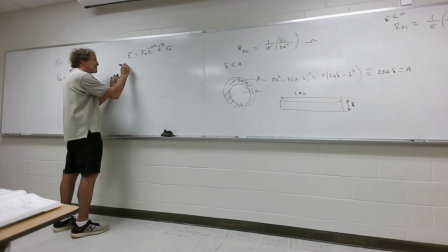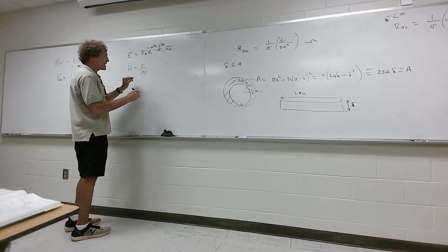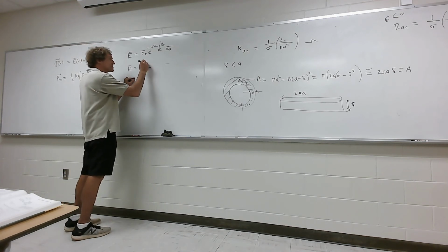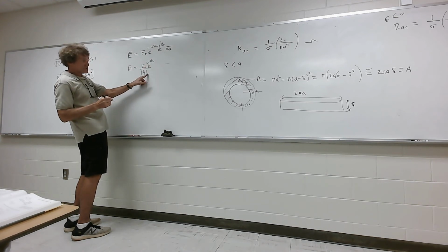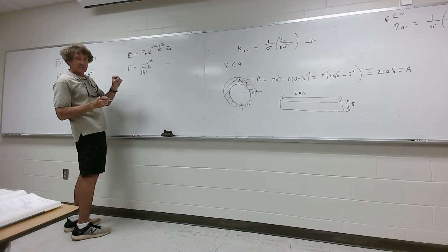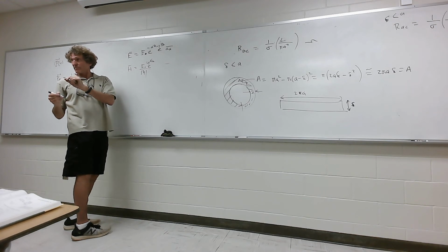The H field that's going to come out of this is going to be E naught over the magnitude of eta. Now the angle is interesting because it's going to be e to the minus j, whatever this angle is, on eta, but it's got a minus because it was downstairs, I brought it upstairs, so it's going to be minus that angle. Do you all follow me, class? What I'm doing here?